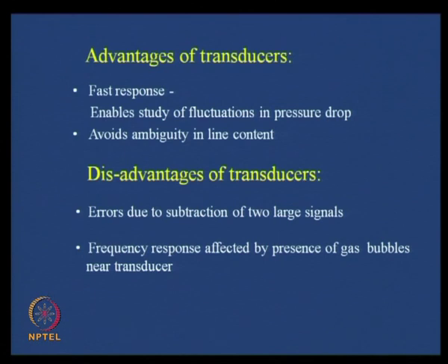Now, if this is a problem, then what will we do? Instead of subtracting the two signals, suppose we take the two particular signals in one particular device. Say suppose with tapping lines, we connect the two signals to one particular device which has a diaphragm, and the two particular signals are connected to two ends of the diaphragm. Then by the diaphragm movement, if you can measure the differential pressure, that will be more accurate. Instead of measuring this pressure and then subtracting them, this is definitely going to be more accurate.